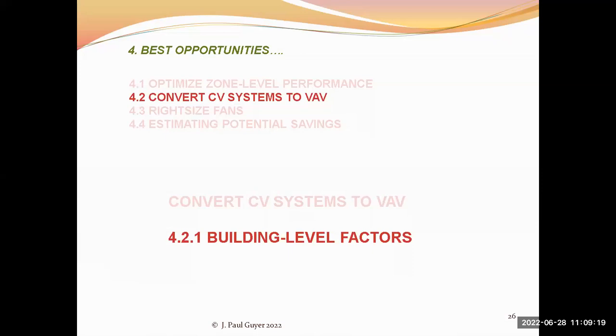Checking the dampers, as an example. Are the dampers on the HVAC system accessible? Are there access hatches so that the contractor can get at them?